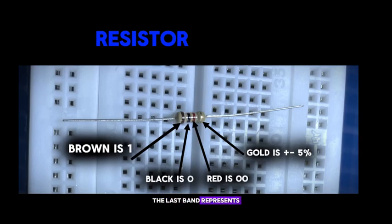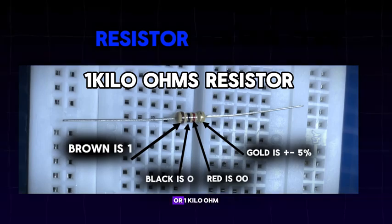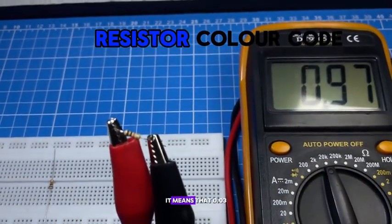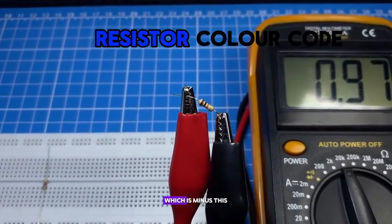The last band represents the tolerance level, and the tolerance level of the resistor is plus or minus 5% tolerance. So in this case, the resistance value of this resistor is 1000 ohms with plus or minus 5% tolerance, or 1 kilo ohm. As you can see on the multimeter, it is showing 0.97 kilo ohms. It means that 0.03 kilo ohms is the 5% tolerance, which is minus.